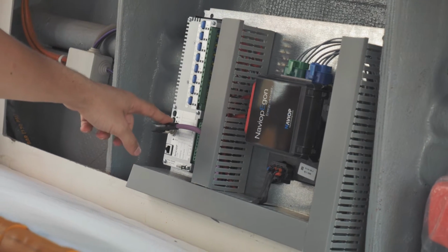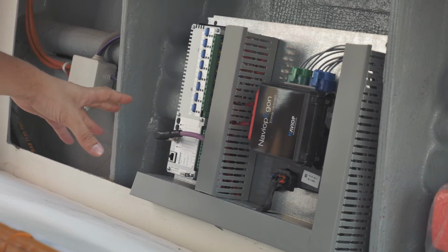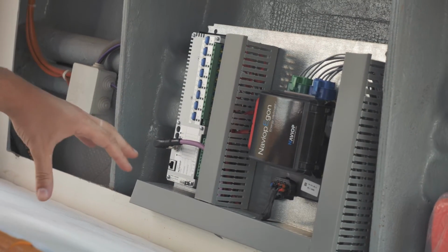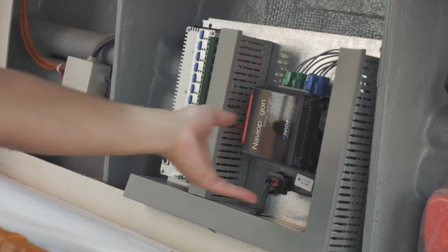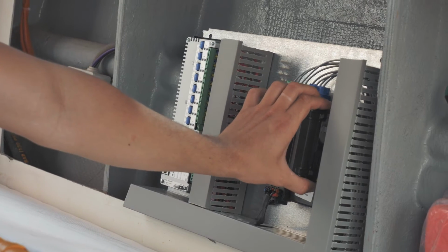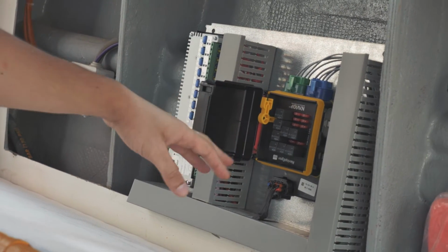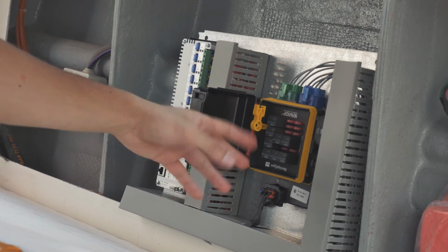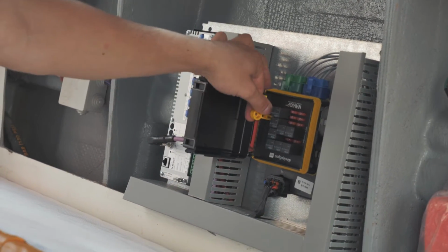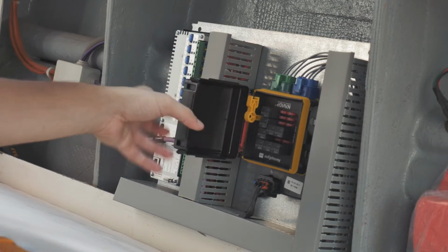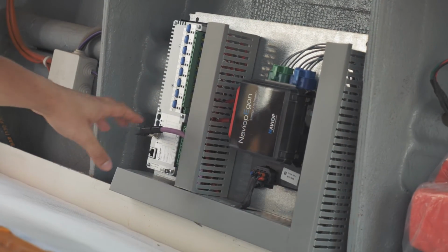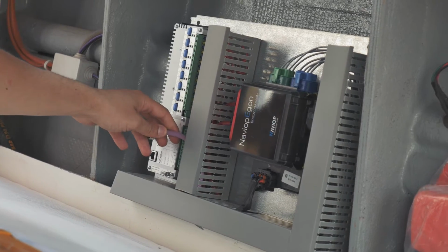Everything you have seen in the Simrad panel passes through and is managed by these 2 components. One, the Nova light board. This is the unit we use to manage the lights and also the light dimming in this case. And this is the Agon board, the unit we use to manage the loads and all the appliances. As you can see right here, you can see all the fuses and the relays, and it's very easy to replace a component once it's broken. And all these units speak with the system through the CAN bus line.